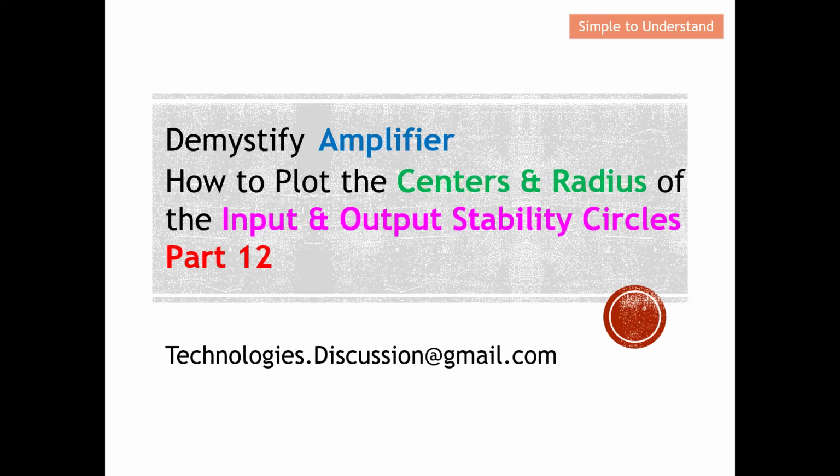When we plot this stability circle, we have two sectors. One sector is called stable, and the other is called unstable. Therefore, this specifies the condition where the amplifier should be so that it will be able to work in a stable region. Basically, this is why we need to plot this stability circle: to distinguish the zone where the amplifier will be stable or unstable.